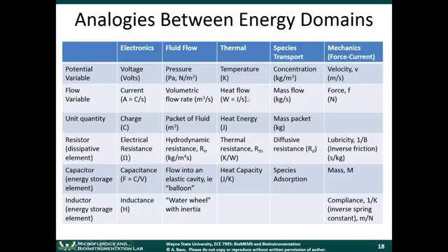Okay, and when we talked about the different resistor elements, here you're talking about the electrical resistance, here you're talking about hydrodynamic resistance, and here you're talking about thermal resistance. Again, in my opinion, quite intuitive to understand. In the mechanics domain, when we make equivalent circuit models, there are two different analogies that we can use.